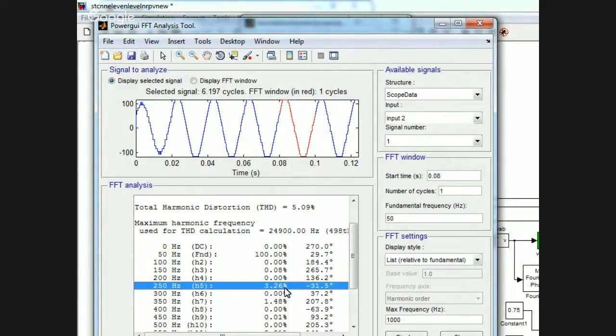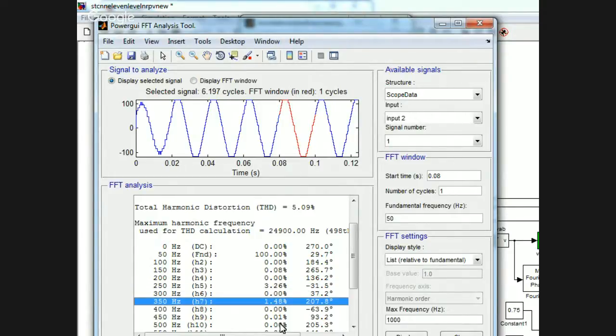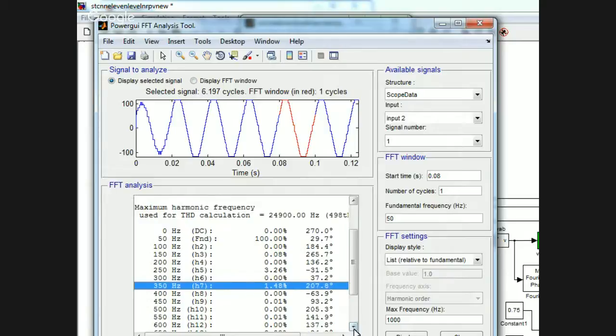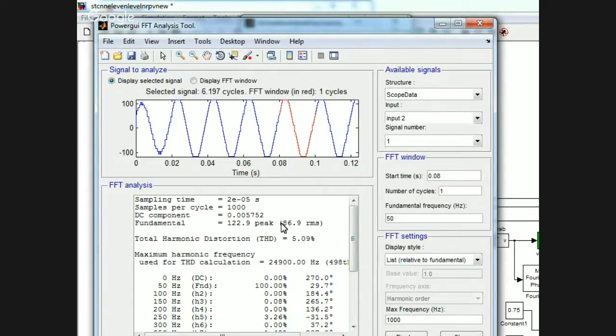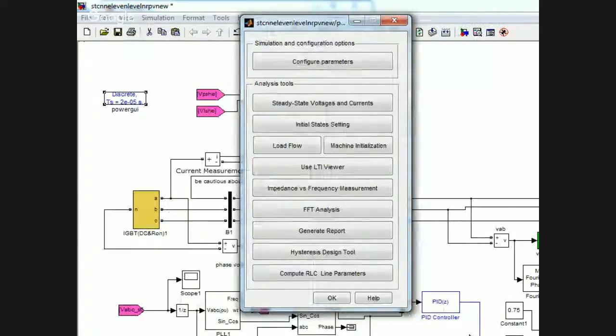When you solve it correctly, if you have taken the objective function correctly, our main aim was that the fifth, 7th and 11th harmonics should all be made 0. If they come to 0, your total harmonic distortion will also be less than 5%. So when you write the program, you have to be very careful how to do it. So this is about neural networks.